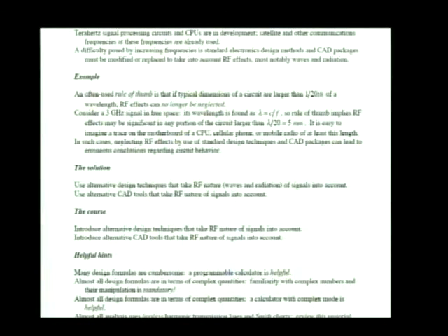And that is, if a typical dimension in the circuit that you're trying to analyze is larger than a 20th of a wavelength, then you can't use low-frequency techniques.